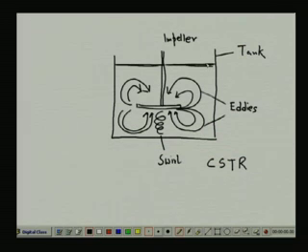Whenever the oxygen gets in contact with the top surface, it dissolves, and this top surface is getting saturated with oxygen. So, this top surface has to be refreshed, that means the lower water will go to the top like this, so that it will get more and more oxygen. Now, if we increase the speed of the impeller in this CSTR, the frequency of water coming from the bottom to the top, the refreshing of the top surface, will be faster and faster. If it is fast, more and more oxygen will be dissolved. If you lower the speed, the dissolved oxygen concentration will also decrease.